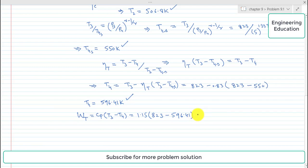So simplifying this, we get 260.57 kilojoule per kilogram. Also, for finding the compressor work, it is Cp into (T2 minus T1). This is basically the Cp of the gas side and it is for air.